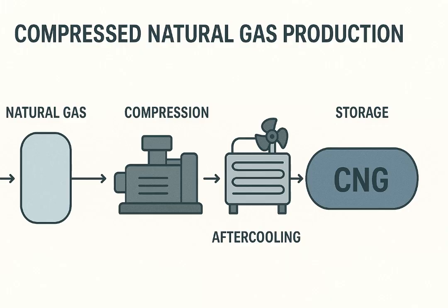7.3.2 Here's how real gas concepts apply to the CNG process. 7.3.2.1 Compression of natural gas. Boyle's law and real gas effects. The process of compressing natural gas is governed by Boyle's law for ideal gases, which states that at a constant temperature, pressure is inversely proportional to volume.